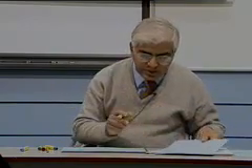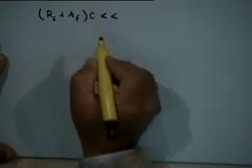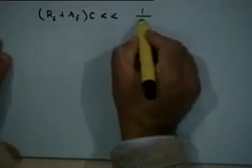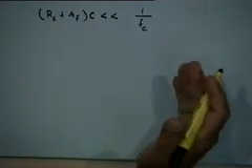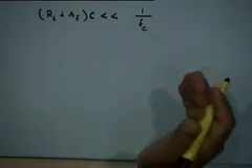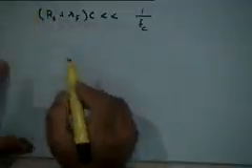So the point is that for the charging time constant, the condition that we should have is that this time constant is much less than the reciprocal of f sub c, which is the time period of the carrier wave, right? It should be much smaller than that, so that the capacitor immediately charges the moment the diode starts to conduct, right? It follows the half cycle of the carrier wave as it comes during the positive half cycle, right? So this is one condition that is required.